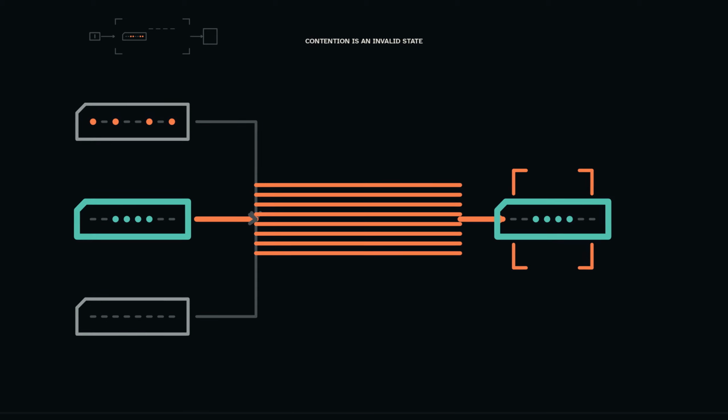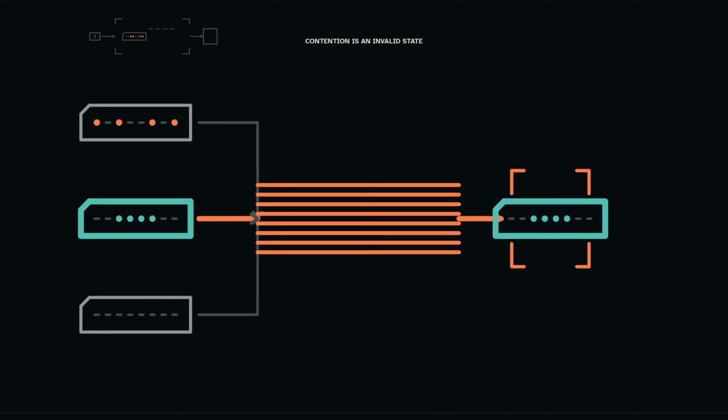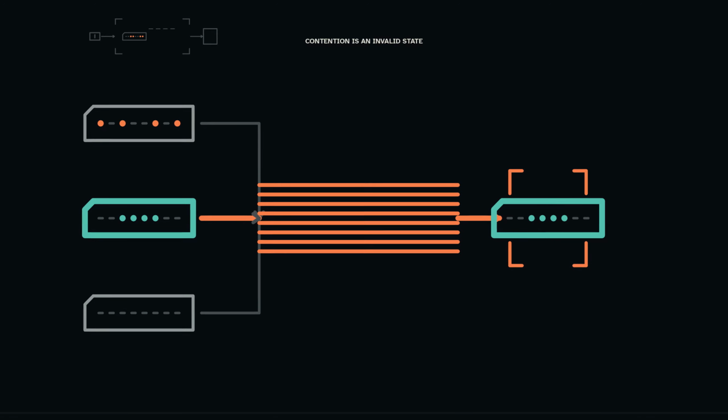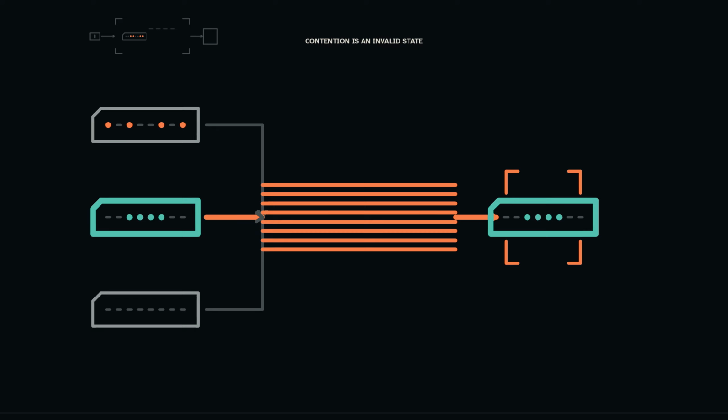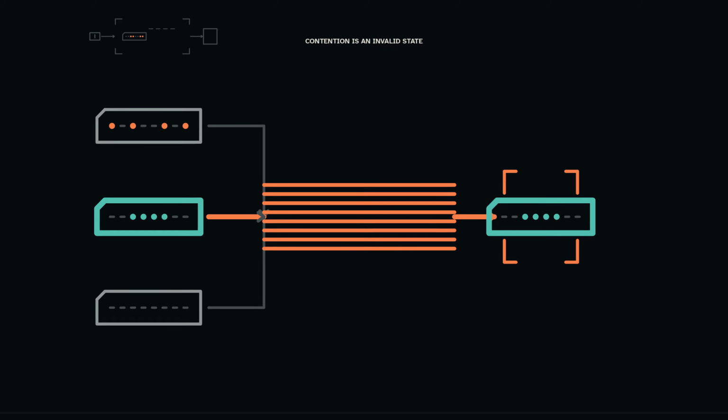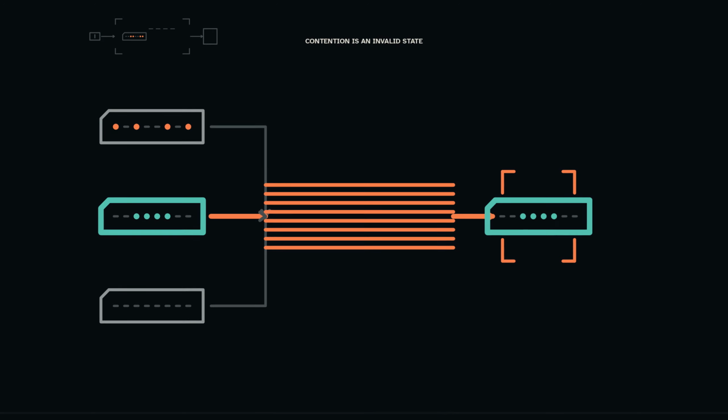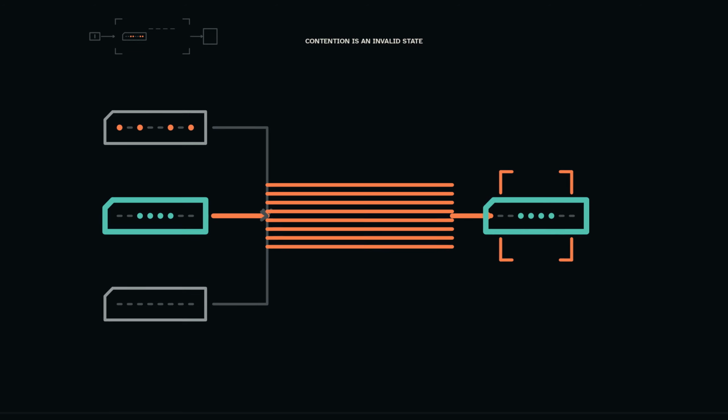The bus is settled to hexadecimal 3C, R1 is selected to receive, and the clock edge has not yet arrived. Predict both states. Before the edge, R1 still holds its old byte. The bus may already display hexadecimal 3C, but a route is not storage.